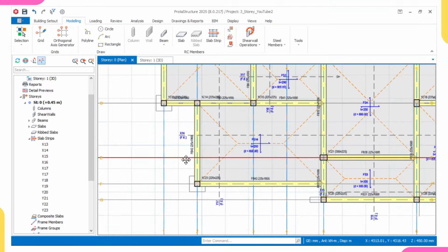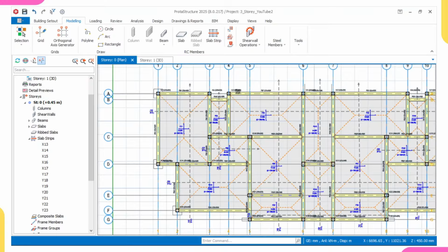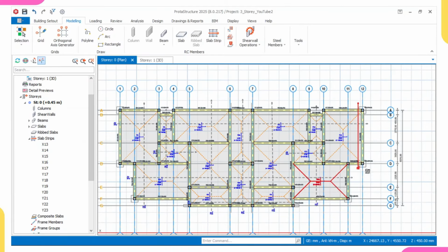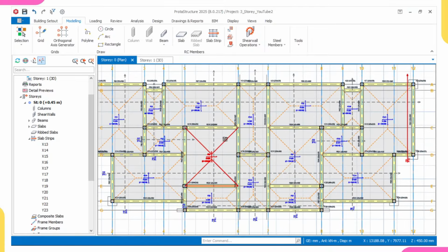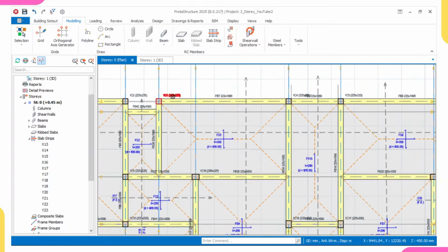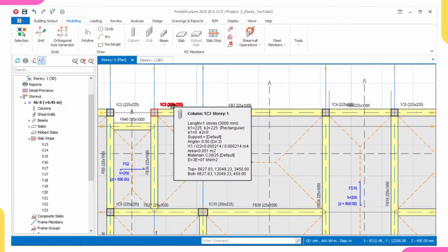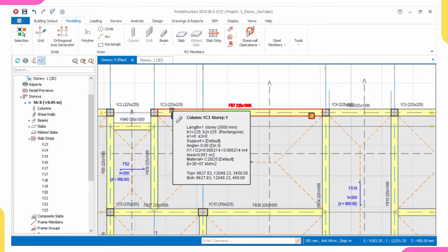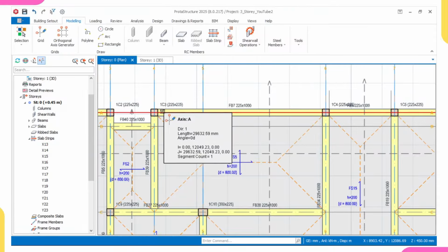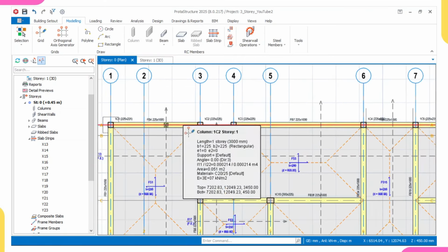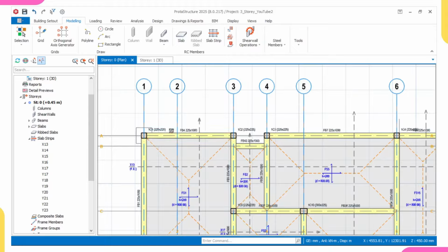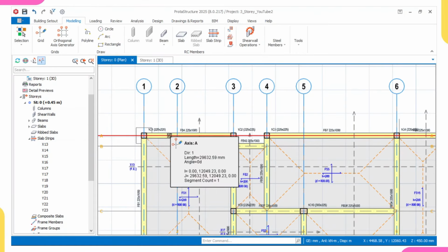So for that reason, we'll be introducing a cantilever slab around the whole edge of this beam raft foundation, so that it will help spread the load coming to this structure evenly to the soil. If you do not introduce this slab, I bet you most of the time it will fail. Or if you don't want to introduce the slab, you can introduce a very high beam depth, but I'll advise you just introduce a slab. We'll be going with the minimum cantilever length of 500. Then if it fails, we'll come back and increase it again.